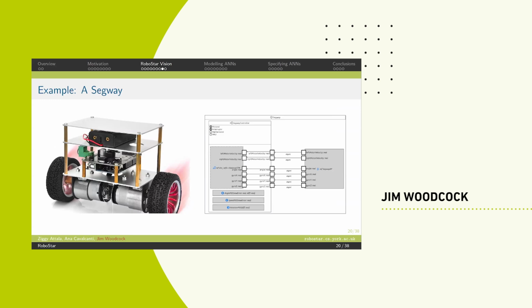They've got two wheels and a handle at the top, and it's one of the first. The control law is an inverted pendulum. It's one of the first exercises in a MathWorks course where you're developing some PID controllers and so on. So it's an inverted pendulum. There's two motors, one on each wheel, and it's continuously putting torque on the wheel in order to keep the device upright. And the particular little example we've got is a miniature version of the Segway.